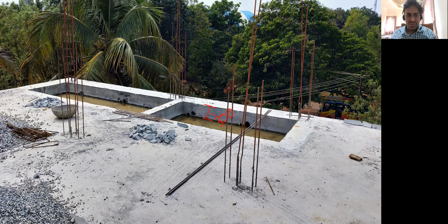So we will take the plumbing lines. You can see the sleeves given here. These are for the plumbing. Once the plumbing line goes in, we fill this particular area with sand, or let us say you can fill that with brick beds. Brick beds are the broken bricks. With that we are going to fill it, and then match this with this level. But that will be done only when the plumbing lines and all are taken up. Otherwise, this is how it looks practically once we do the casting, right?